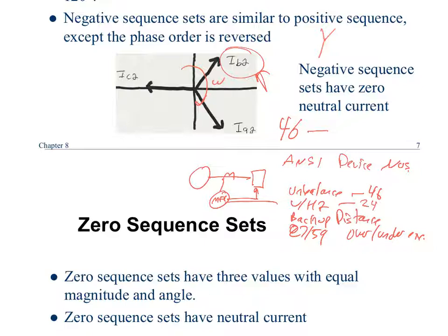So you use negative sequence for unbalance. It works beautifully, and it can be set very sensitively because the negative sequence should be 0. If it goes up to 10% or some non-zero value, and you can't set it too low, right? Because there's always going to be some unbalance. But you can't set it too low because there's also some inaccuracies with all this measuring stuff. You could say, oh boy, I got a problem here.